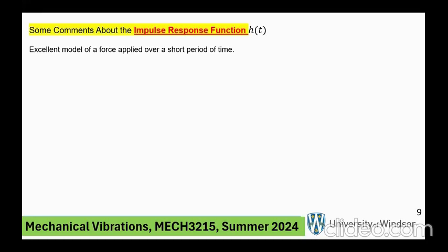However, it's an excellent model for a force that applies during a very short period of time. This represents the response due to a force that is 0 everywhere except t equal to 0, where it shoots to infinity. However, the area underneath it, if you can visualize it, is 1. Not a true function, actually, but an excellent model for a force over a short period of time.